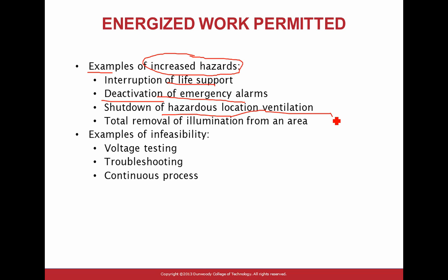You do a lot of hazardous stuff, venting, working with chemicals. If it stops, you expose the workers to a hazard. That could be classified as shutdown of hazardous location ventilation. Or shutting down the whole lighting system, removal of illumination from an area, will expose people to a hazard. So you can work on it energized. That's for increased hazard.